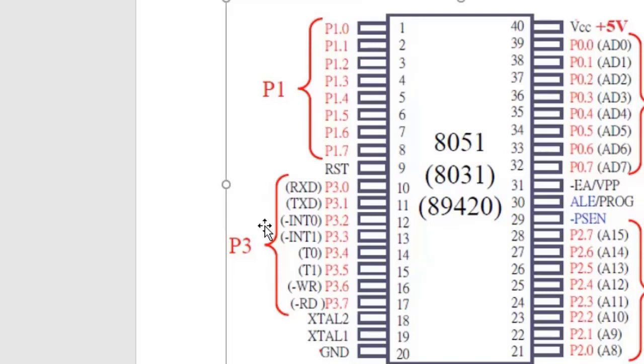And if I want to control the timer externally, then also we can use these P3.2 and P3.3 pins, and in that case some external signal will be given from here to run the timer, and after that we will use the set bit timer run operation, and we will use the timer.